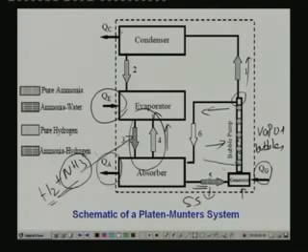Okay. So, that is how the whole system works, and you can see here that we are rejecting heat at the absorber, rejecting heat at the condenser, supplying low temperature heat at the evaporator, and high temperature heat input takes place at the generator. In addition to that, you also have to supply certain energy for the bubble pump to operate. So, here energy is required for generating the vapor as well as for operating the bubble pump. And remember that the total pressure is constant at every point. When I say constant, there will be small differences because of the gravity heads and all. For example, if you look at this one, pressure at this point will be higher than the pressure at this point because of gravity head. Okay.